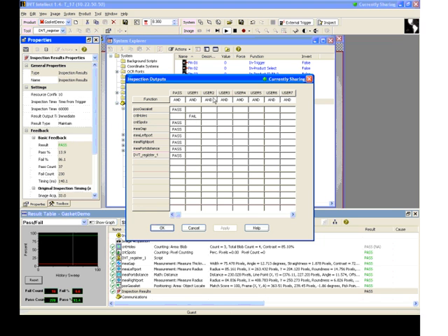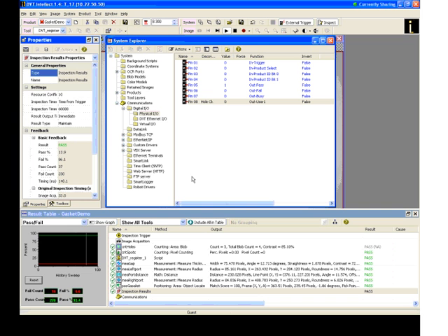So that's user 1. I have 16 users. As you're going up to user 16, and we'll follow these a little bit later. But notice user 1, when the count holes failed, I want it to go high. So here we are indicating that out user 1, I've assigned it to pin 8. I could assign it to any of these pins. But we're going to assign it to pin 8 right here. I just happen to call it a hold check in the description, which again is something I listed in the Properties tab. But it is going low right now.